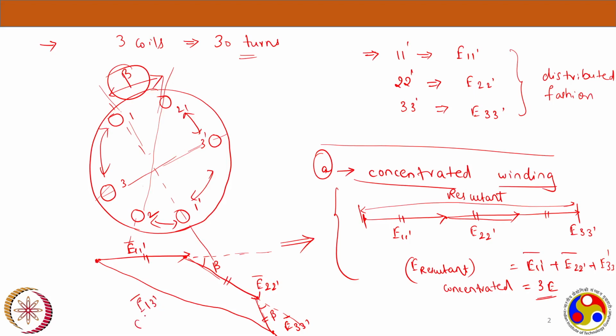This is the resultant. Now you can easily relate that it's not just an algebraic sum, but there is an angular factor coming. Now, with a good phasor diagram, we will see how mathematically we can calculate this resultant, and then we will get a picture of what is the total resultant voltage in a distributed kind of winding. So that's what I will try to make here.